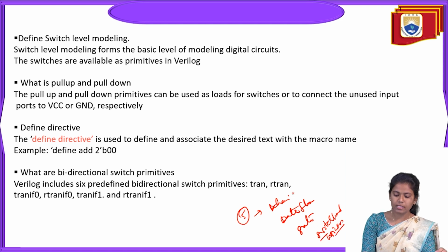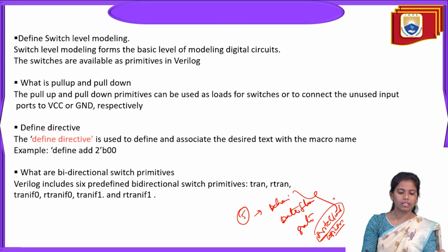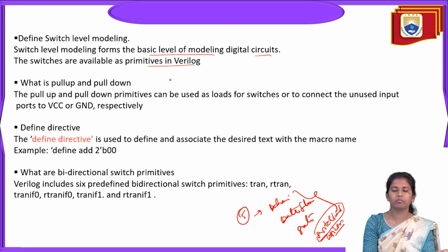As these are the 4 modeling styles which play a vital role in Verilog HDL, we will be discussing the definitions and the different terminologies which come across in switch level modeling. So what is switch level modeling? It forms a basic level of modeling digital circuits. The switches are available as primitives in Verilog.